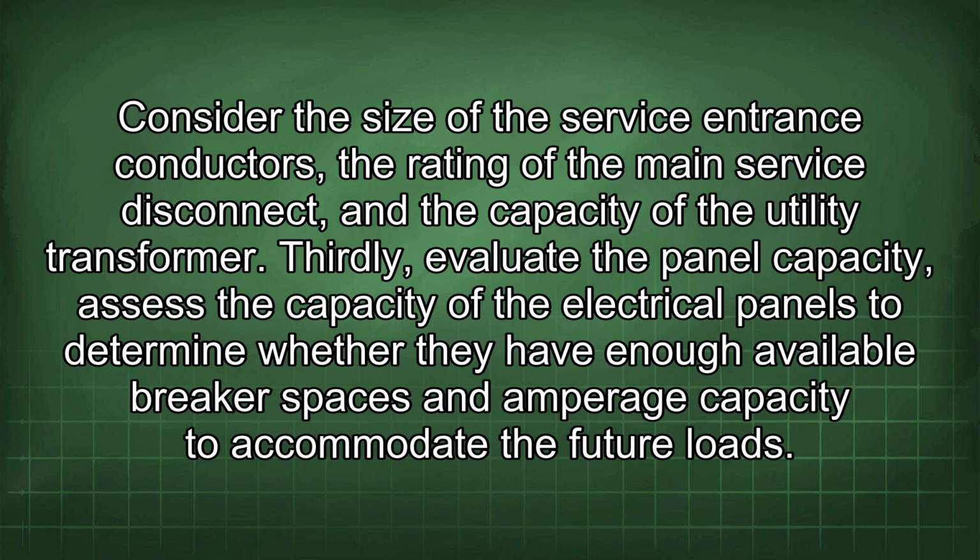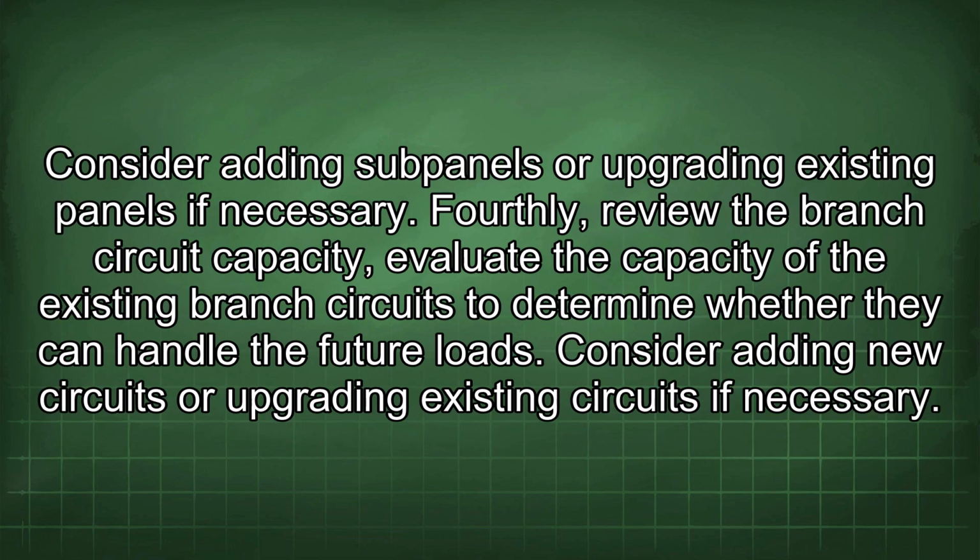Thirdly, evaluate the panel capacity. Assess the capacity of the electrical panels to determine whether they have enough available breaker spaces and amperage capacity to accommodate the future loads. Consider adding subpanels or upgrading existing panels if necessary.